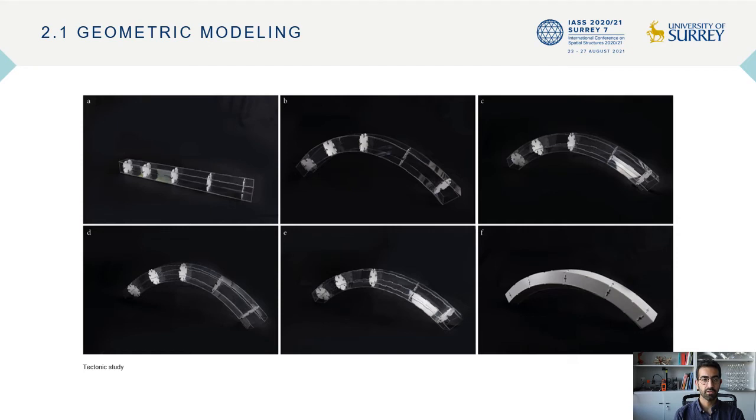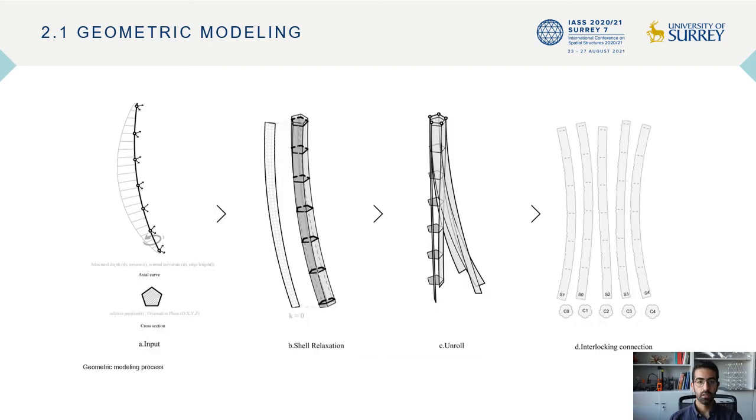Next, the abstracted construction principles translated into a digital environment. The computational workflow mainly deals with creating developable surfaces based on the actual NURBS curve and the stiffener geometries. The ruled surfaces generated by sweeping the edge of the stiffener plates run through a spring-based relaxation to have a constant zero Gaussian curvatures. The surfaces are then unrolled to the 2D configuration for applying the interlocking connection details as well as engraving manufacturing data.